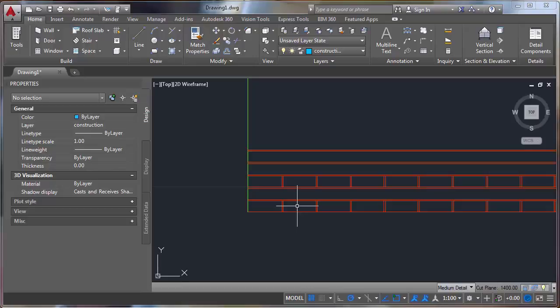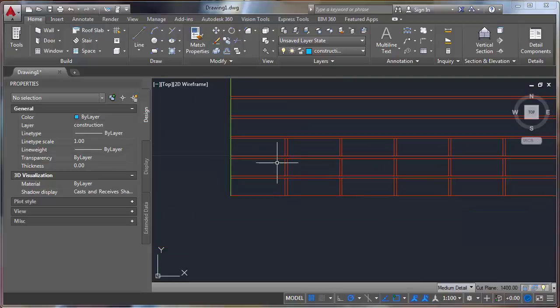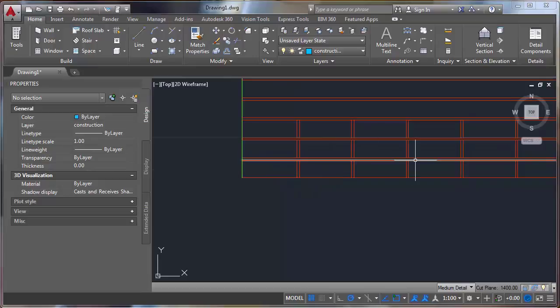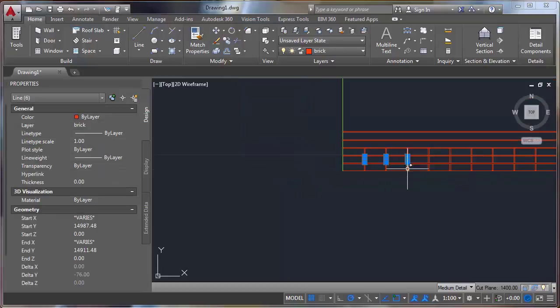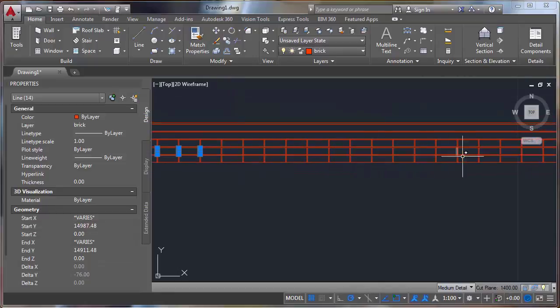And it might be as easy as, let me copy. A nice little trick is previous. If I hit P, it'll select those previous objects, and I'll copy them up here. Now I'll type move, which is this key here, and I'll select previous. Nope, we're going to have to actually select them. So I'll just carefully select them. And not everything is super easy. Sometimes you actually have to do some work.